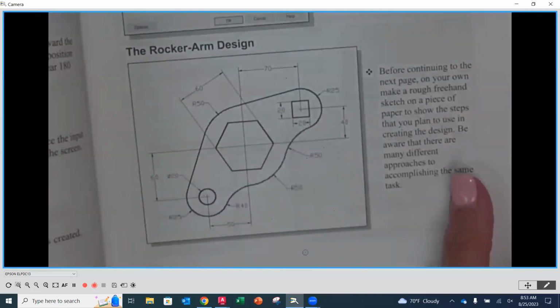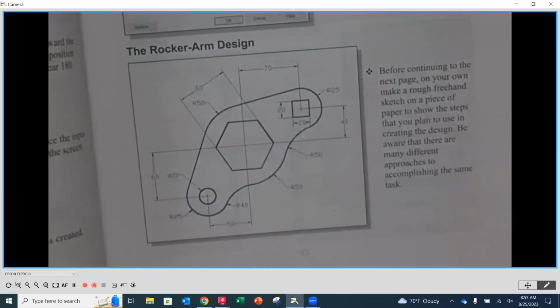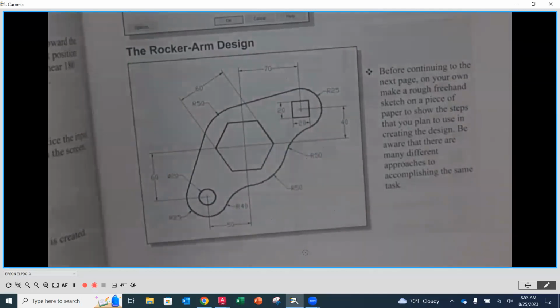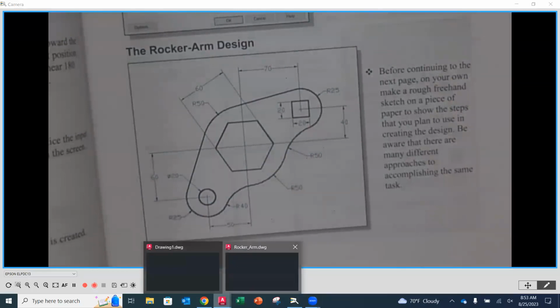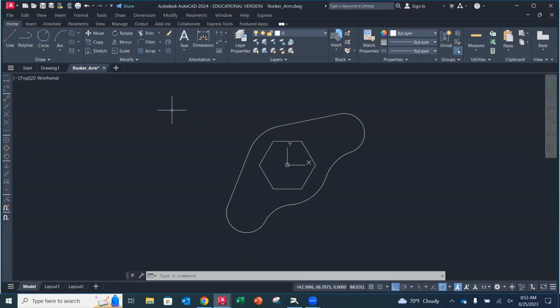Now, I could draw this in as a square if I wanted to and just put lines all the way around. But what's nice about a polygon is if you remember, it said specify the center. And you'll notice that this square is located by its center, okay? We would have to offset and figure out the distances away. But since we have a center there that's going to be shared by a feature we already put in, then we might as well use the polygon and it's going to get us there quicker.